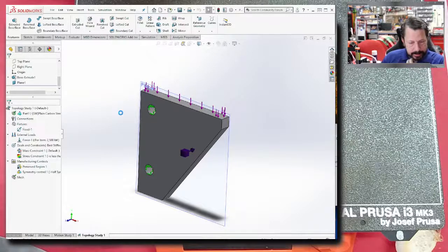But I wanted you to see the actual model that gets created from this. It is a lengthy process for iterating and chopping away at the finite element mesh that it creates. So it basically runs a simulation, removes some material, runs a simulation, removes some material, runs a simulation, trying to get to that goal. Now that I'm thinking about it, I probably should have made a much less aggressive goal. Remember, we did 65% weight reduction, and that might make it iterate for a while.